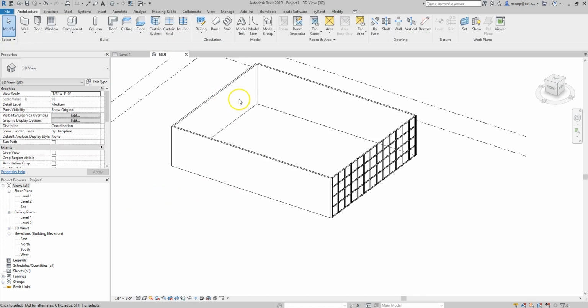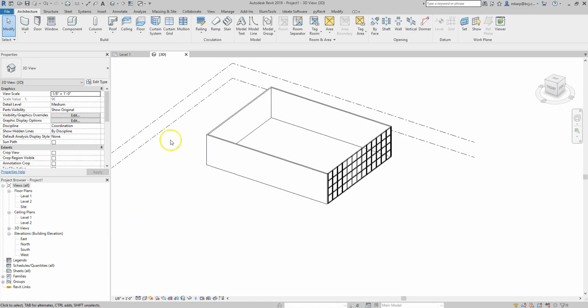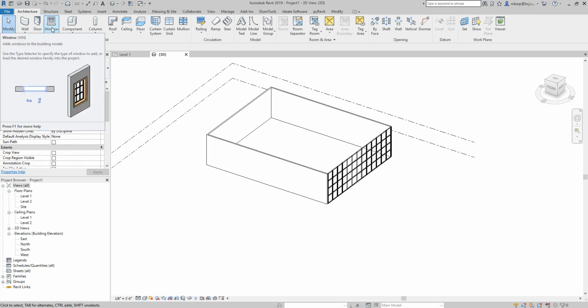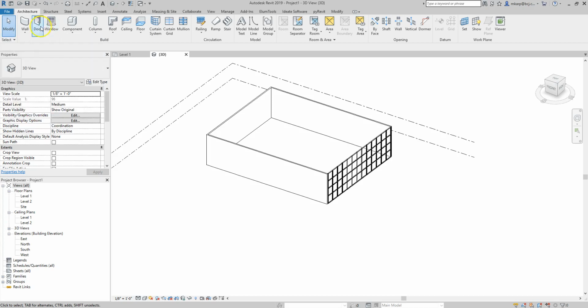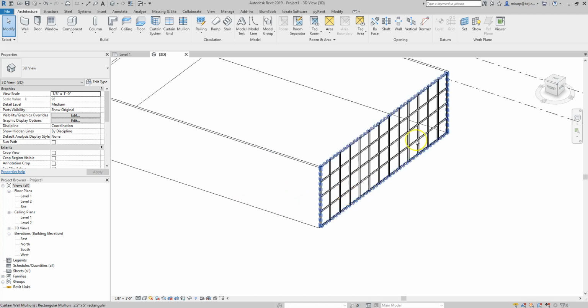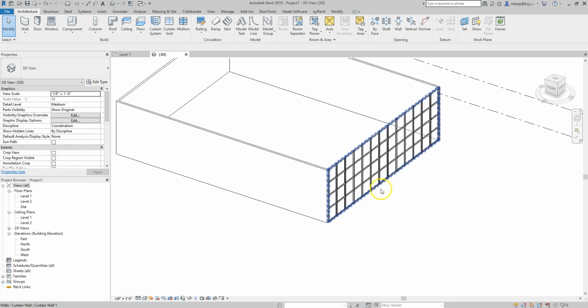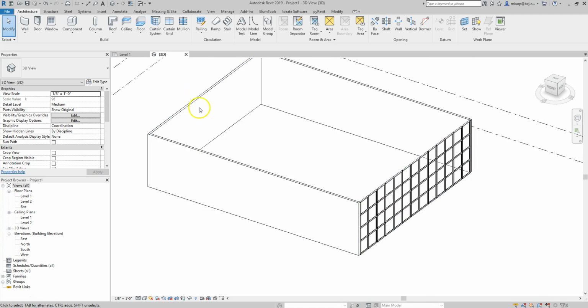What we're going to focus on mostly now is loading in the RFA family types. Those are doors, windows, and a variety of other things. Structural steel, we'll go through the list just so you can take a peek. But we're going to start with doors. We're going to load in some doors that we could place into this wall. Then we'll do some windows, and then we'll talk about what it's like to put a family into a curtain wall, or a door family into a curtain wall.